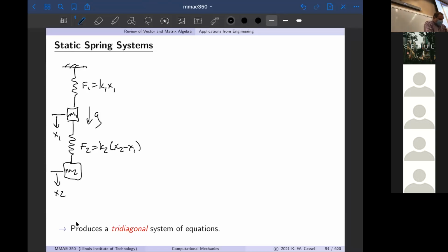All right, so how do we analyze this? Well, we analyze it the same way. We do free body diagrams. So in FBD, let's call this 1 and 2, each of the two masses. So for mass 1, and then we'll do a free body diagram for mass 2. For 1, once again, you take the thing, in this case the mass, and you isolate it.